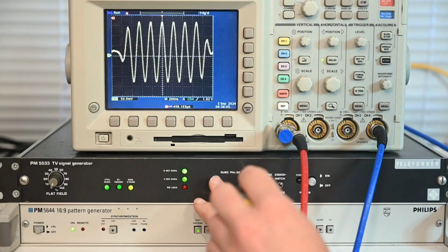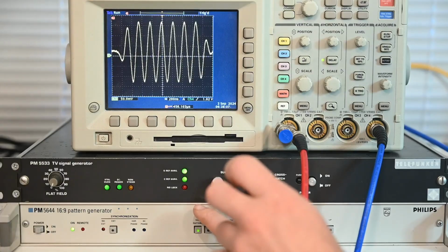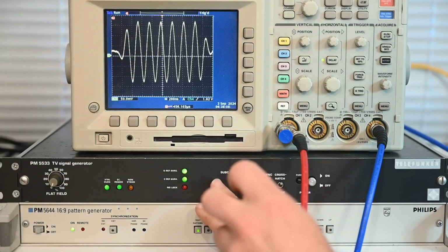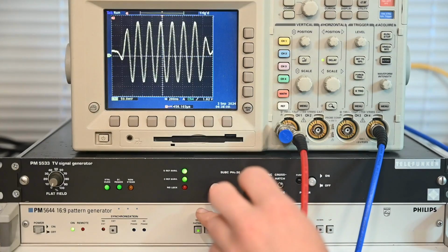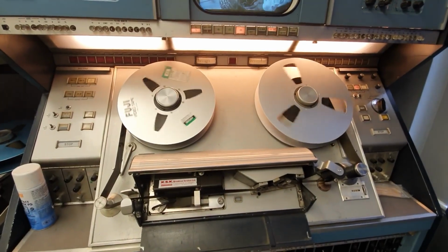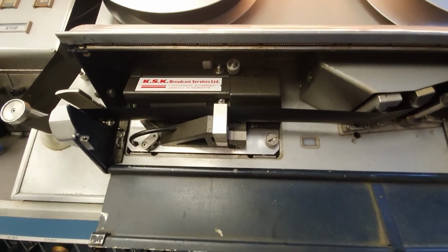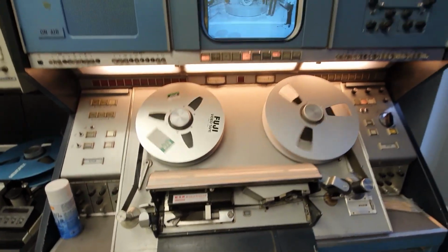A rather interesting implication of all this is that the shortest possible recording of PAL video, which can be played on a loop, is 4 frames, or 2 for NTSC. Take a minute to think about the implications for video tape recorders, where you are trying to do a synchronized cut from a live feed to tape, and your color subcarrier is on tape and you have no control of it. Anyway, that's a topic for another time.